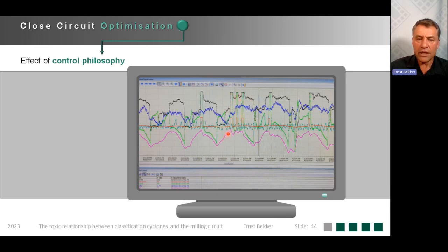The purple line is the sump level, normal discharge sump level. And then the red line is the power from the pump. So as the sump level started to fluctuate, the pump will have situations where it's speeding up and then it will overload the capability of the mill cyclone. The cyclone will start to rope and will send coarse material to the overflow. You can open up another cyclone, but later then you have to close another cyclone.